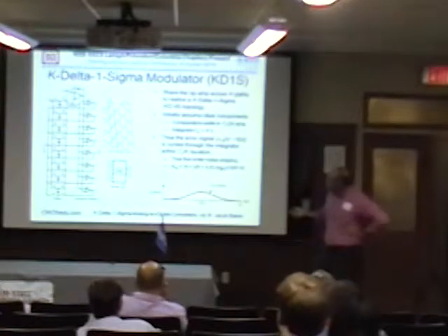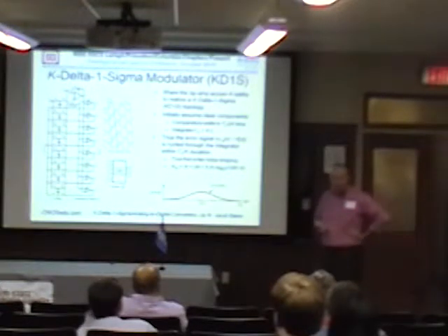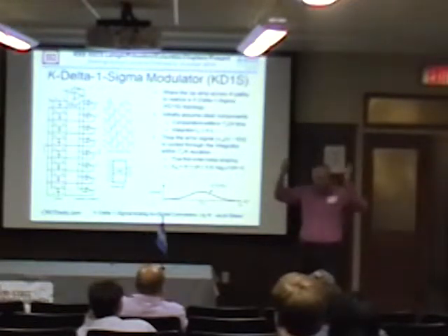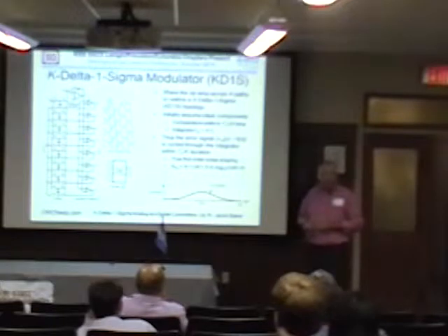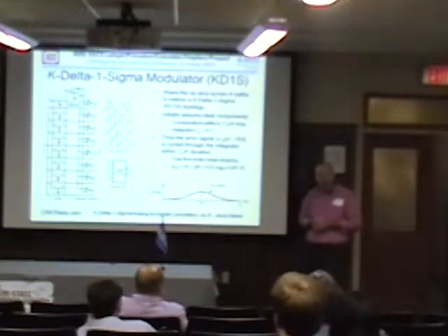The other thing is that when you do this, if you can use like 2 inverter delays, and you can get like 10 picoseconds in a modern process, your effective sampling rate can then be 100 gigahertz. Well, in a small little area, even if you have imperfections, you're starting with 100 gigahertz, so your ability to digitize something at 4 bits or 6 bits using the topology is quite high, with such a large starting bandwidth, with a reasonable bandwidth in the gigahertz range.